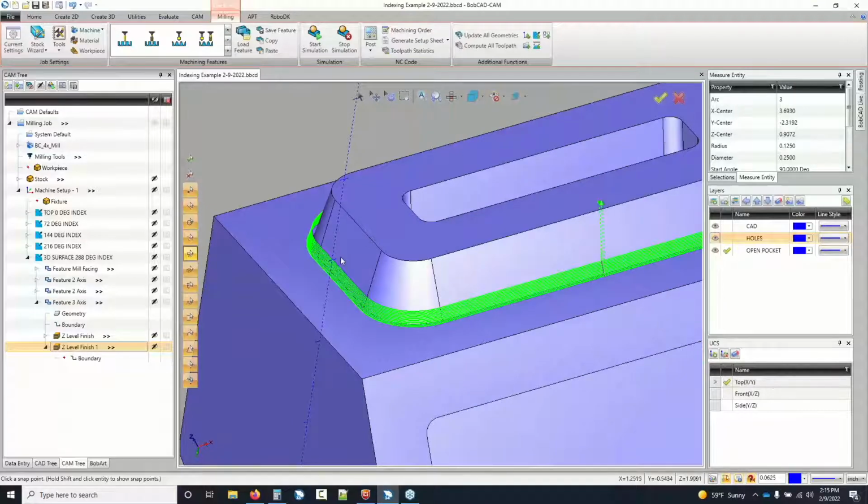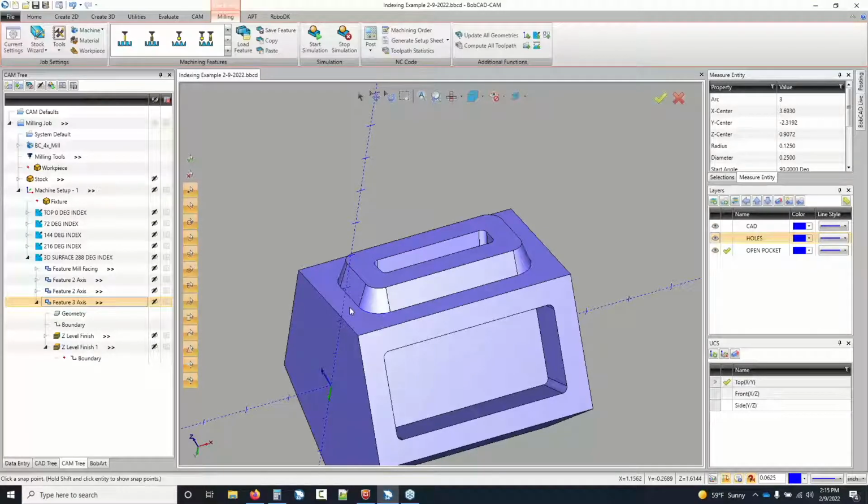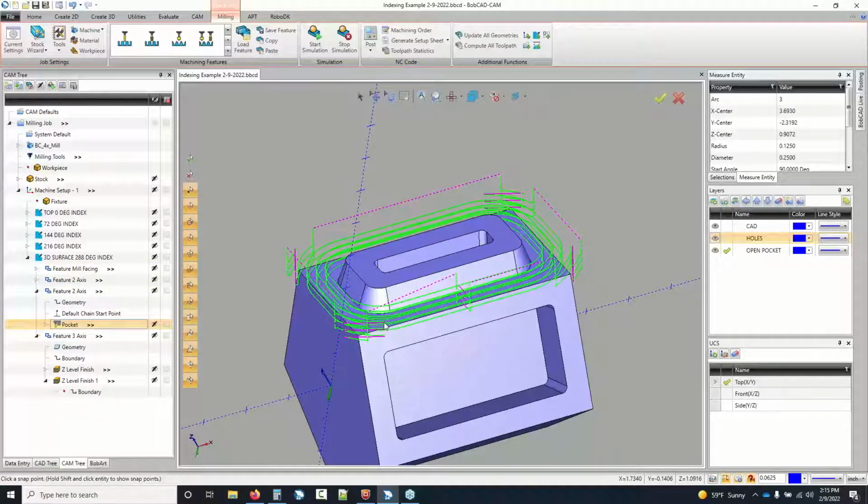Again, Mark said it already. The best way to do it on our original model would have been to add the fillet to the model, whatever's an acceptable size fillet. And then really the way I'd want to run that is on that open pocketing. I'd try to use something like a bullnose end mill that has the radius of the corner in it, so that when I do the finish pass or when I do that floor, it does leave me a nice flat floor, but I could also get the radius into it before we blend the rest of the wall into it. And honestly, it's one of the biggest fights you'll have whenever you use the Z-level toolpath, how to get the floors and the walls to blend together nicely, because you are limited. You're using the tip of the tool and all that stuff.